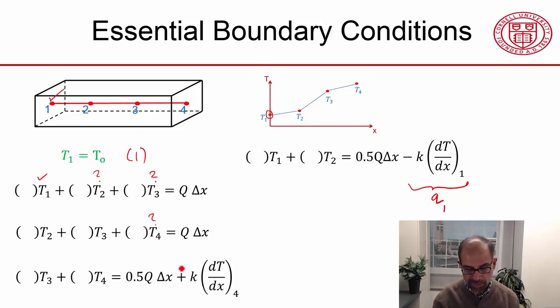So you have 3 equations and 3 unknowns, and so you solve them together by inverting that subset of the stiffness matrix, and that's step 2. In this case, that would involve inverting a 3x3 matrix. Now people are doing ridiculously large problems, 100 million unknowns.